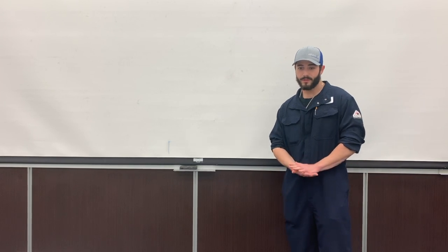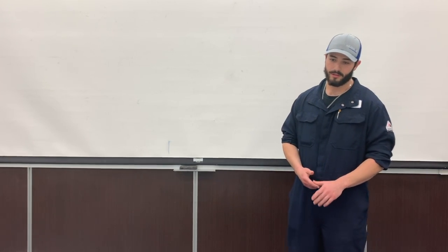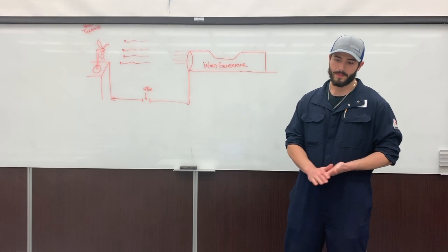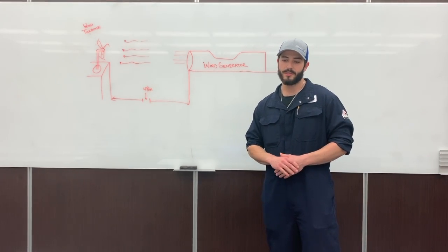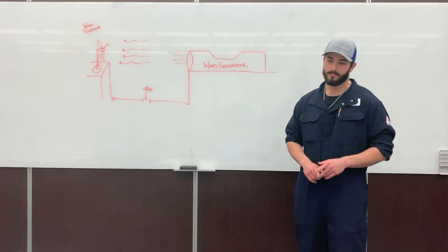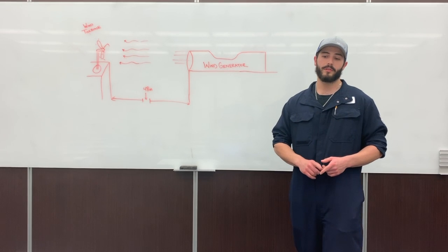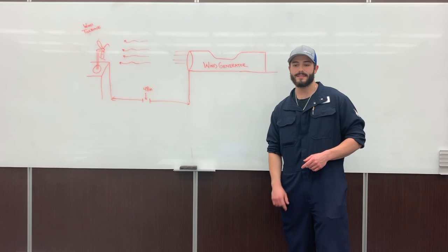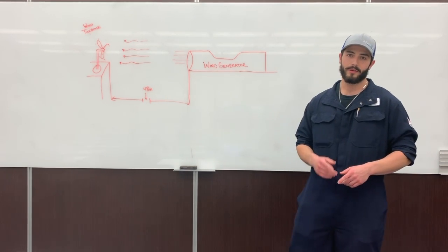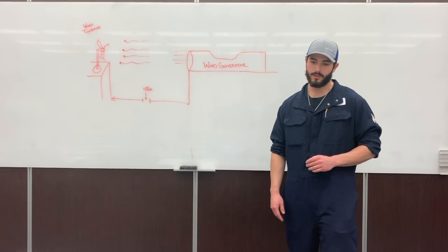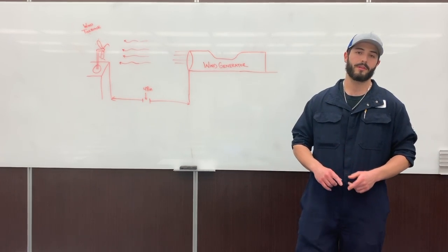So for our setup, we used a wind tunnel to create the wind, calibrated using an anemometer, model PS2174, which recorded our wind speeds. Next, we used an FCJJ29 wind turbine for our actual experiment. It's capable of running 12 blades. We ended up running 3 and 4. The 3 types of blades it has are a custom 28, the NACA 44 and 63. We ended up going with the NACA 44 and 63, and we also had different pitch angles, which were 30 and 60 degrees.